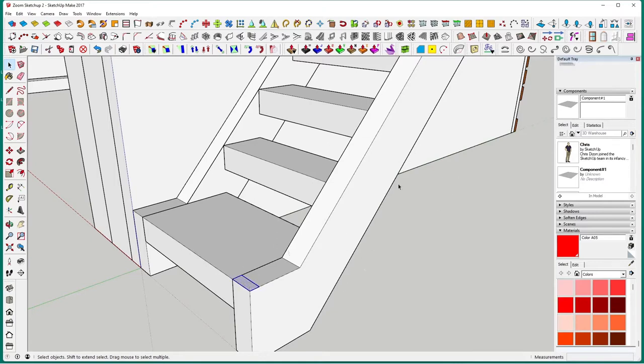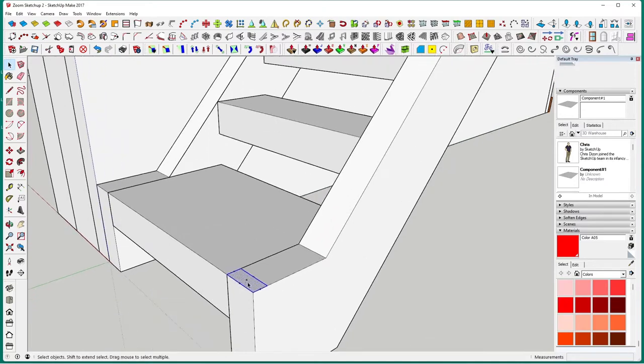There's another little add-on which is Face Center Find. I'm not sure who supplies it, but you can Google SketchUp where you get the downloads from, and you click on here and you put center and it will automatically put a center point in it. So if we double click, Control, click the center point, make a group, and now we want to move it, we can just click and we've got a center point already on there.